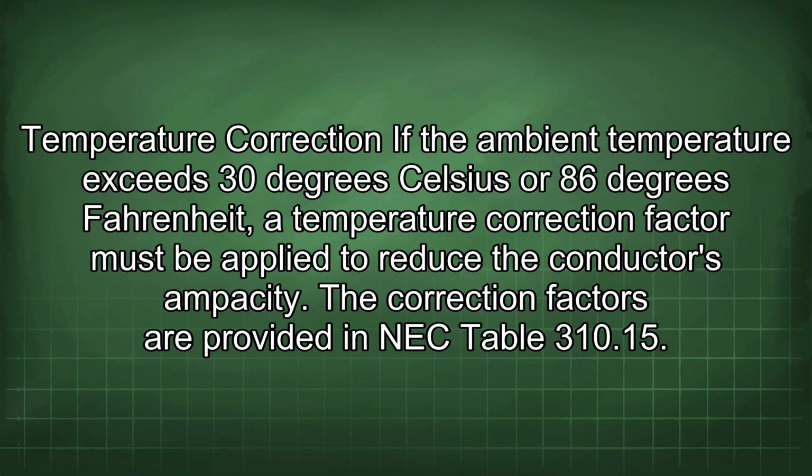Temperature correction: if the ambient temperature exceeds 30 degrees Celsius or 86 degrees Fahrenheit, a temperature correction factor must be applied to reduce the conductor's ampacity. The correction factors are provided in NEC Table 310.15.